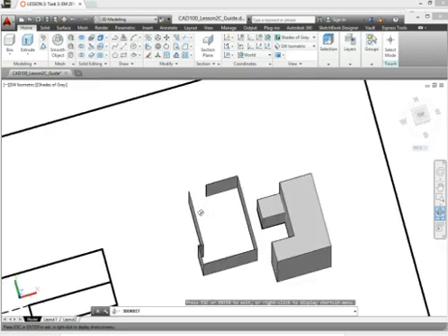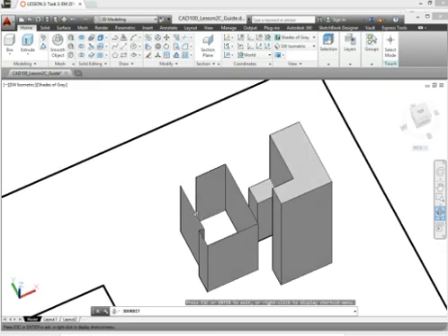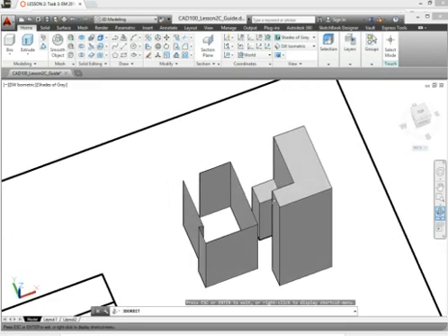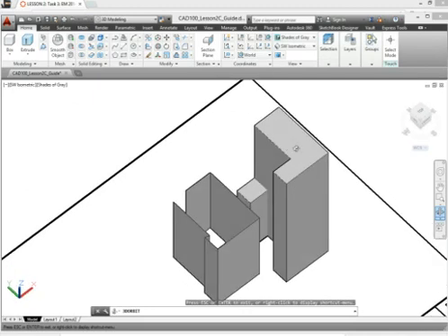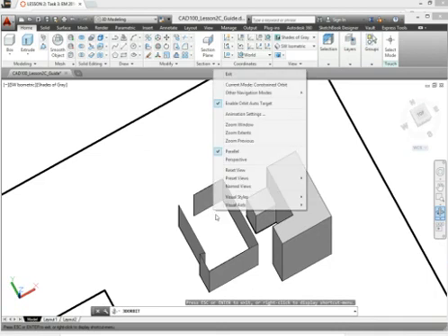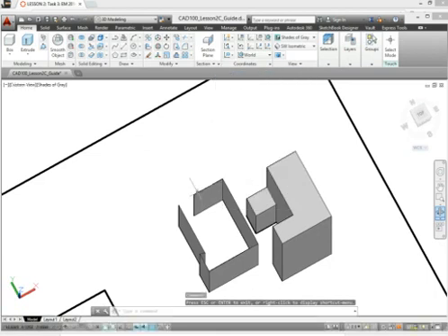See, it's hollow inside because there's a break, but it's cool to know that with polylines you can extrude them. Whereas, of course, if you wanted a solid feature, if the object was closed, it would have been a solid shape. So be aware that if your polyline is not closed, neither will be your extrusion.